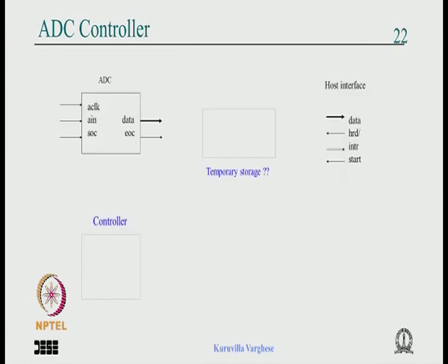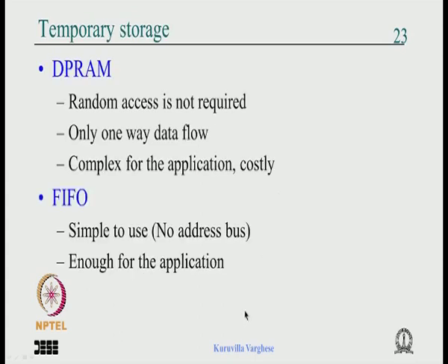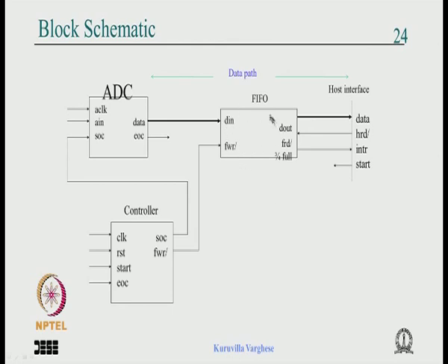What we have done was we have an ADC. Normally an ADC is interfaced to a host CPU, a microcontroller or a processor. What we are trying to do is take the load off the processor by having a controller control the ADC and put the data into temporary storage, and when it is full the host will read it. That was the idea, and we found that the best candidate for this is a FIFO, because you write the data in order and you read the data in order.